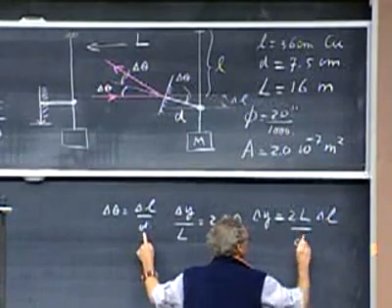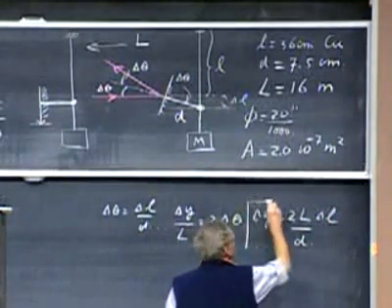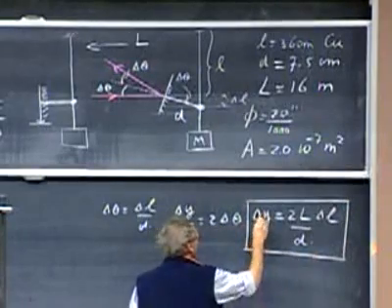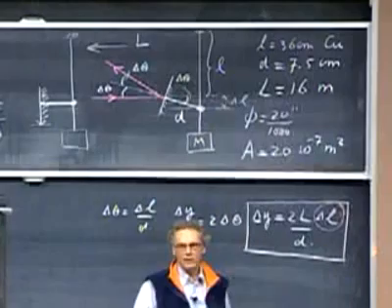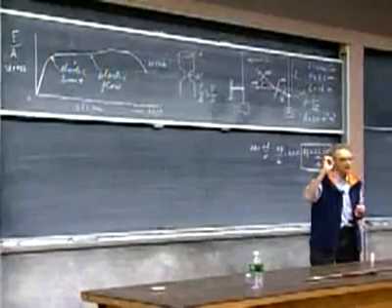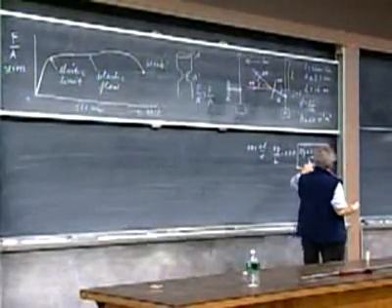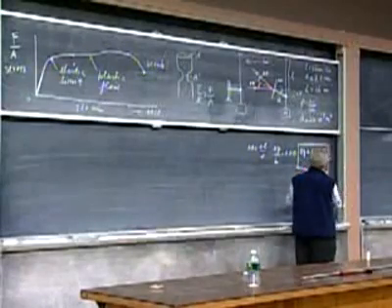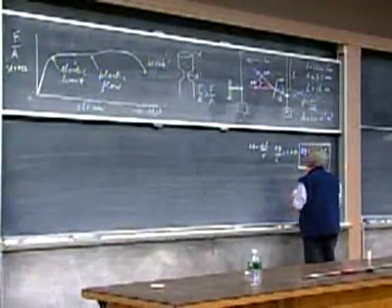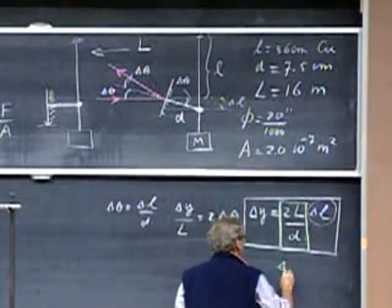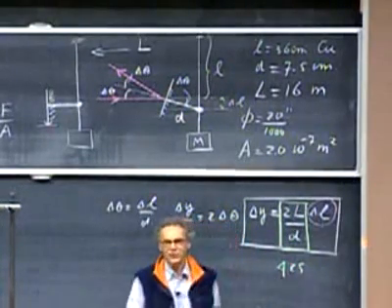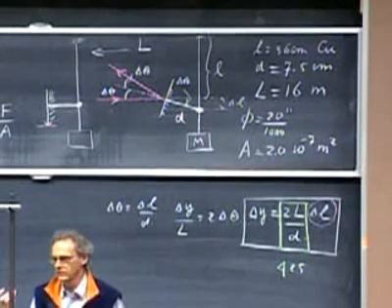2L times delta L divided by D. And look what we have done now. We have converted something that is immeasurable, delta L, which is fractions of millimeters, to something on the wall that we can measure, because this ratio 2L over D, in our case, for the dimensions that I have chosen, is about 425. It's like a magnification factor.